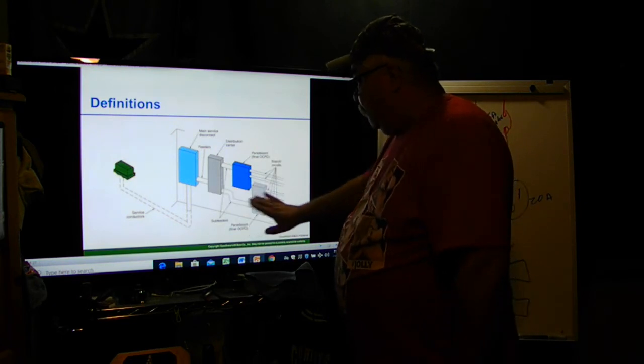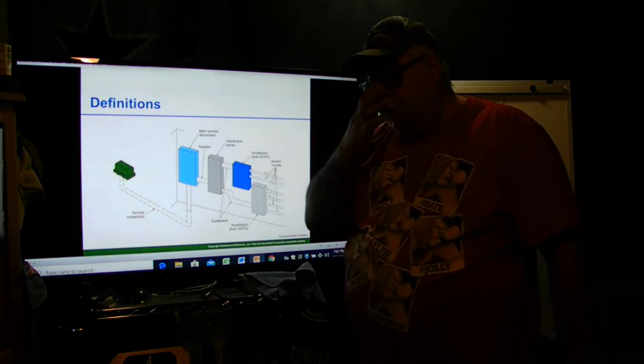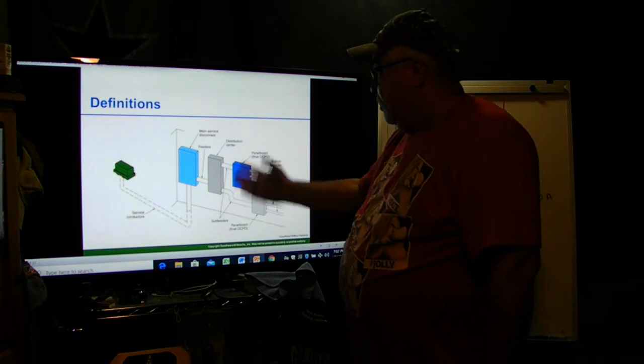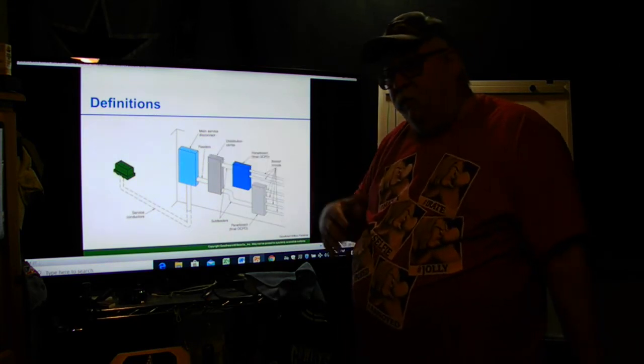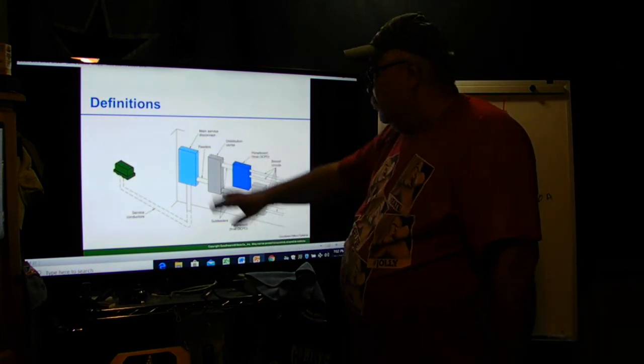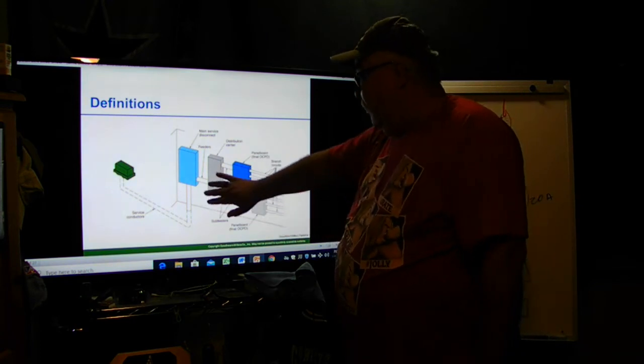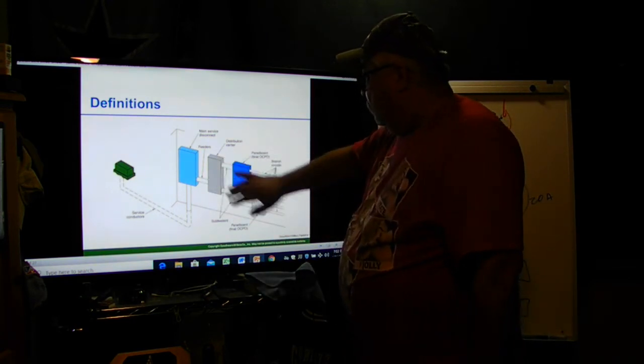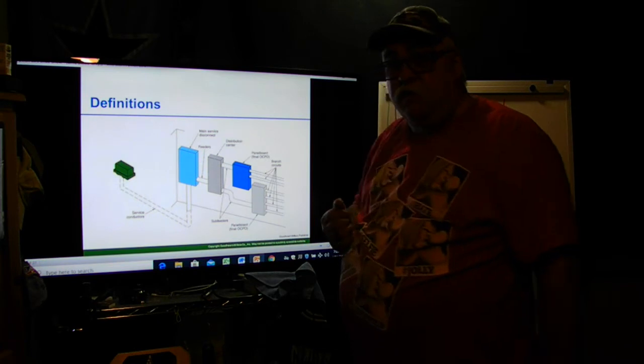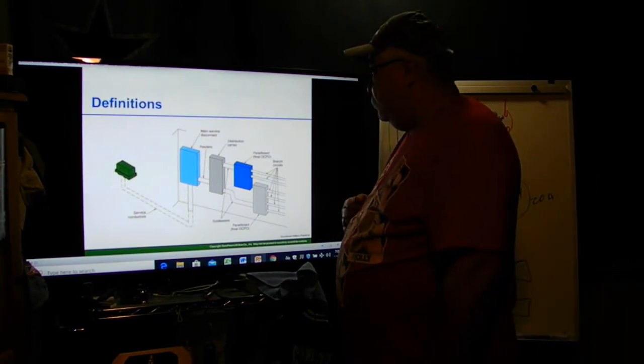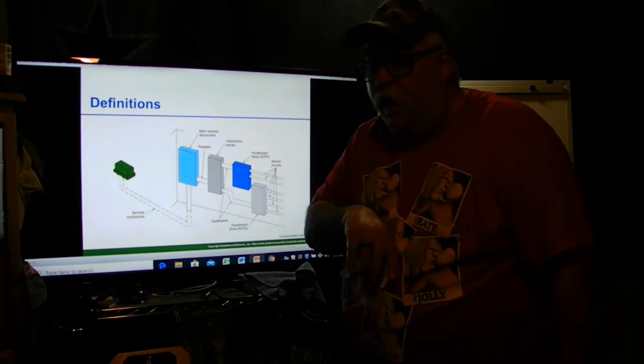Because there is no transformers or anything, this is being supplied by one type of voltage. Let's say it's a commercial with a one phase, with a three phase. So this might be a 120/208 three phase, because both panels come out of the same distribution, so they're both going to be the same voltage. At the school we got a little bit different.